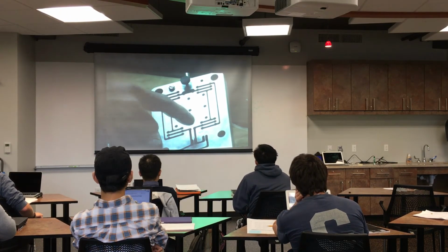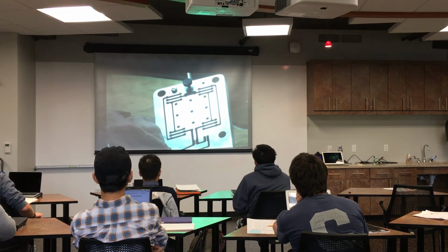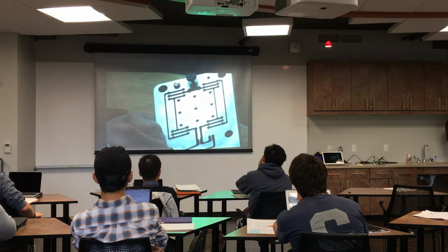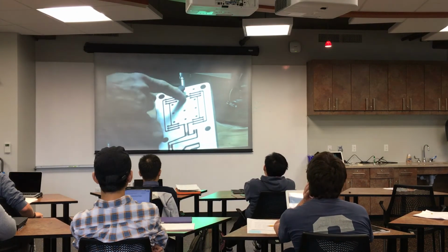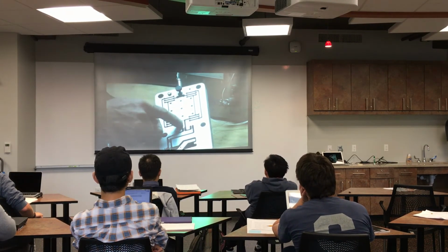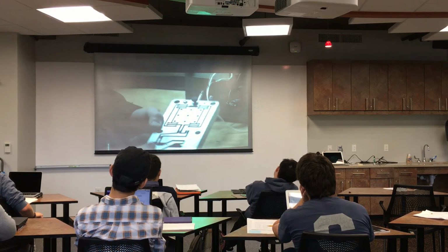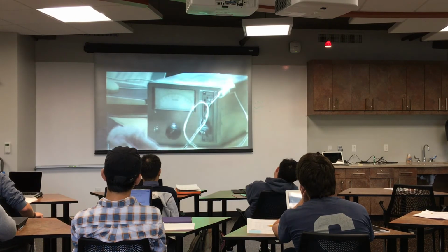So what you have to do is drill and ream these holes, then make all the other cuts with the water jet. Align the water jet to one of the holes and make all the cuts. This way you're going to get, say, a range here of maybe 2 millimeters travel, following a straight line to 1 micron.